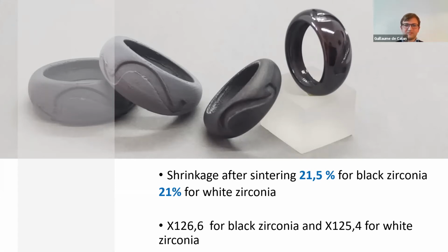And the other materials also have their specific shrinkage, of course. Really not something to forget. If you forget it, you'll find at the end, once you've sintered the part, that it's too small. Well, it sometimes happens, and this is really a loss of time.